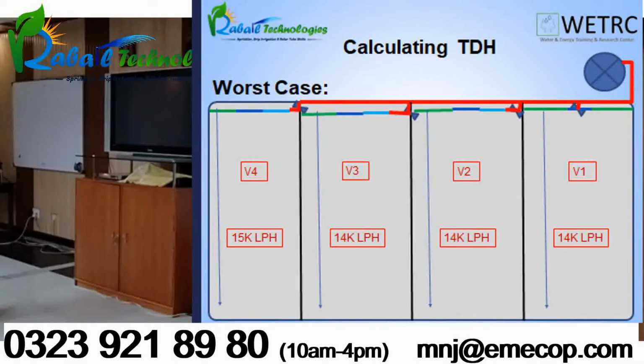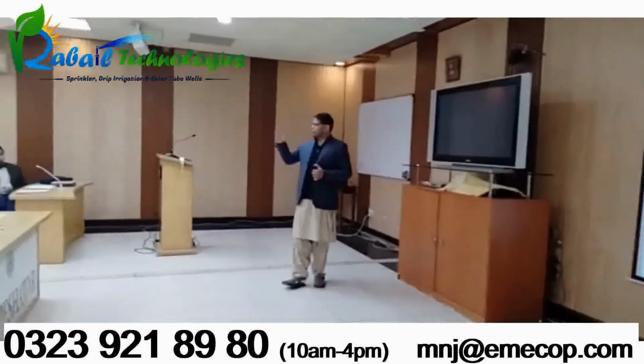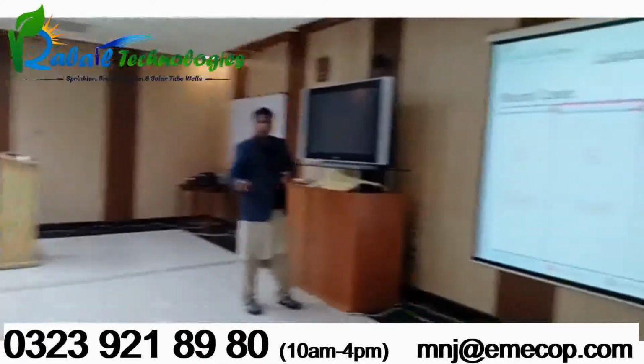So for the entire length, the total flow rate will be 15,000 liter. So we call it main. For the main, the F factor in Hazen-Williams will be 1. For the sub-main, yes, it will be less than 1. It can be 0.2, 0.355, depending upon the table or the equation mentioned for Hazen-Williams in Larry.